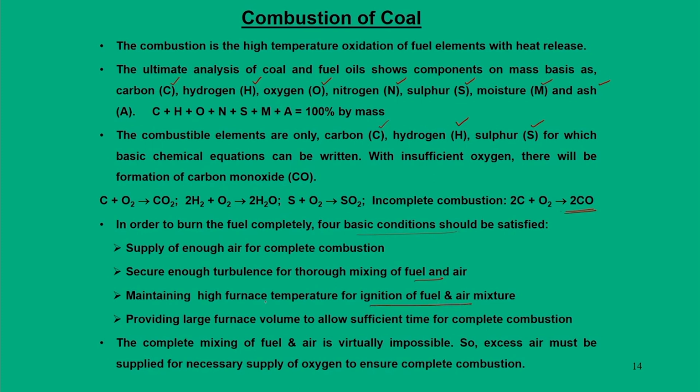So, that means we should maintain very high furnace temperatures. Third thing is that we have to provide a large furnace volume to allow sufficient time for complete combustion. That means we have to allow large area or large volume, so that all the fuel components are burnt completely.